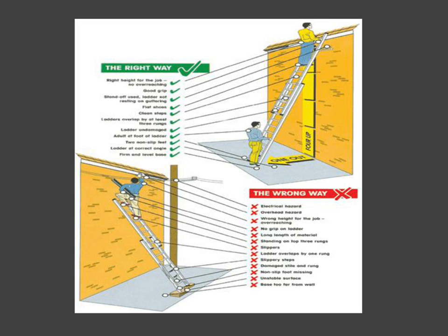And anybody who's doing training of anybody needs to make sure that people have training, even more extensive than this, in ladders before they're allowed to use them. Because in most cases, a ladder is considered a safety device by itself. Of course, if it isn't erected properly, it's not a safety device. It certainly is an unsafe device and a hazard.